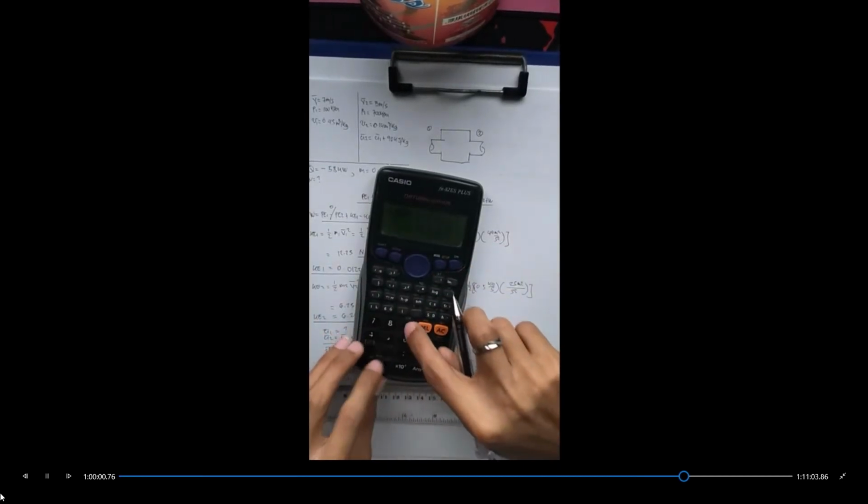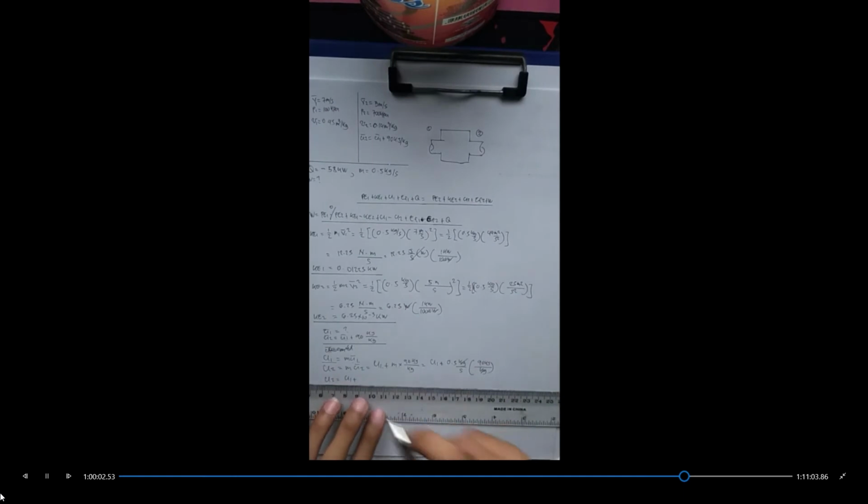So my internal energy 2 is internal energy 1 plus 0.5 times 90, that would be 45. So 45 kilojoules per second. We know that joules per second is in watts. Therefore, kilojoules per second, that would be kilowatts.